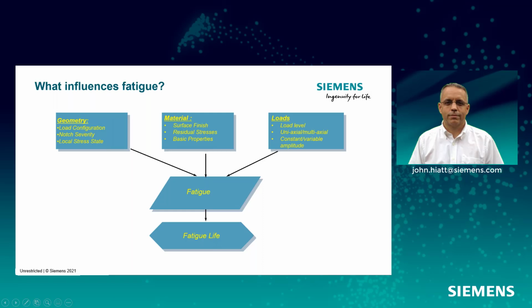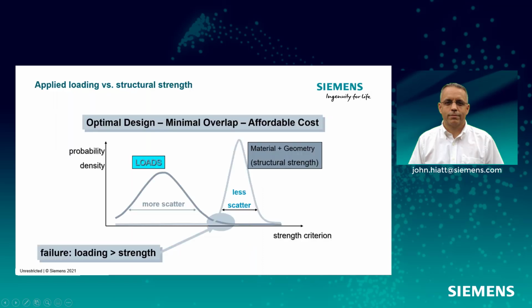If you make parts, components that go in cars or items that people use, drive or mow their lawn or tractors or trucks, then you have a lot more variability. And it's a lot harder to qualify that loading environment. To do a good fatigue analysis, we're going to have to understand all three of these areas: geometry, materials, and loads. So this is a very simplified model.